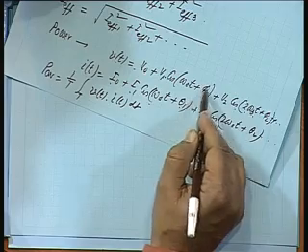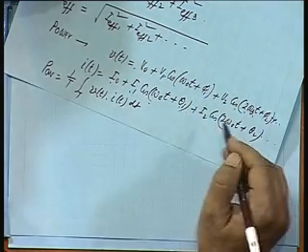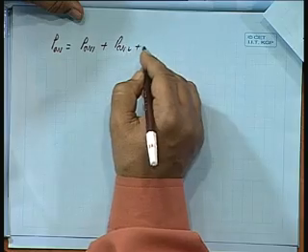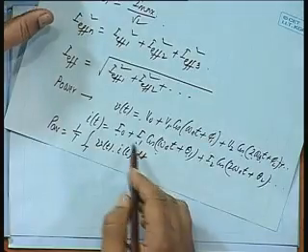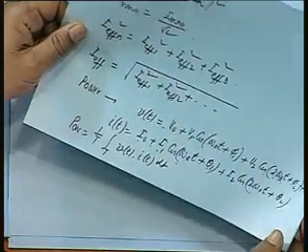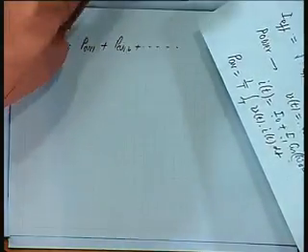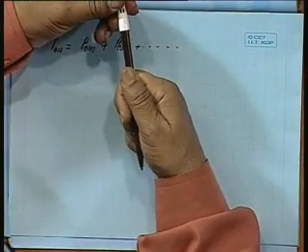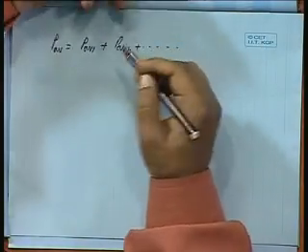So, finally, the effective power will be V0 with I0, whatever is the effective power, then V1 I1, obviously the power is V1 I1 cosine of the angle between the two, phi 1 minus theta 1, phi 2 minus theta 2 and so on. So, that will be the effective value of power. So, P average is equal to P average 1 plus P average 2 and so on, the average of all these individual component powers, that will be the average power.